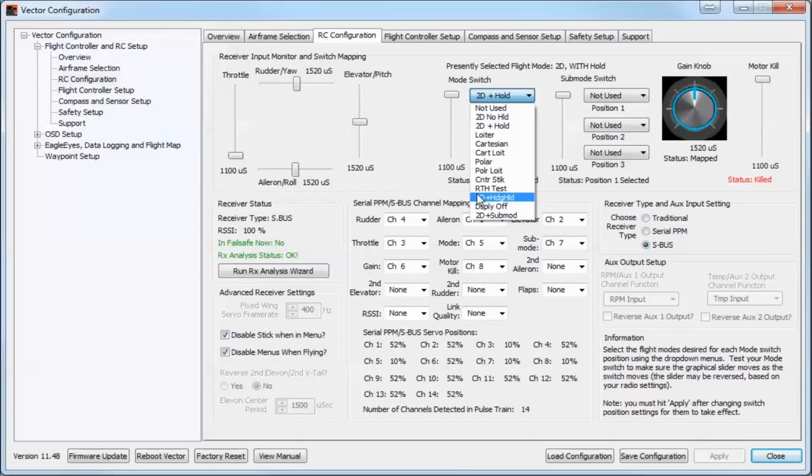you will find that when you actually go forward on your pitch, the multi-rotor is going to tilt forward. If you then bring it back to center stick, you're going to find that it will stay in that attitude. To correct it, you've got to do a reverse input, so you've got to actually come all the way back down in the elevator and you've got to actually self-stabilize it. So it really is for people who are used to flying in manual mode.